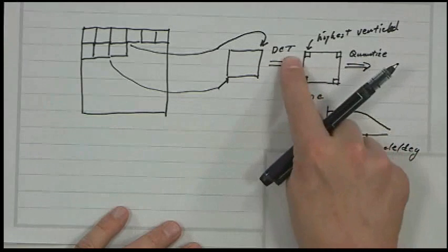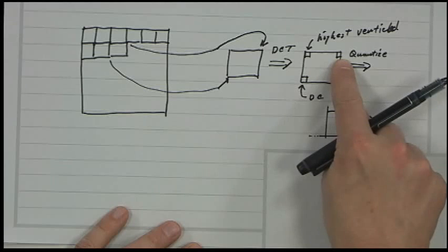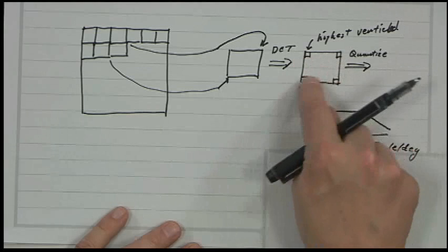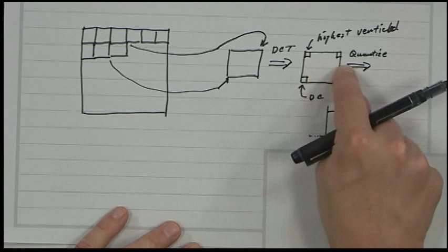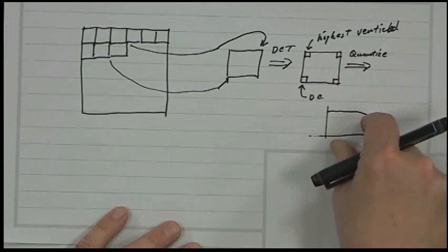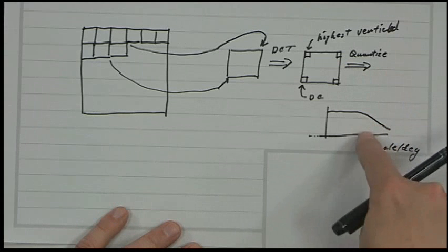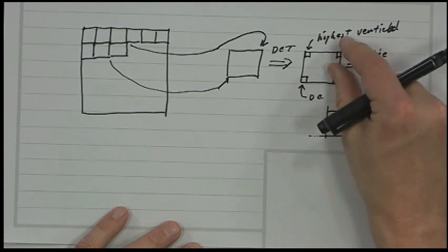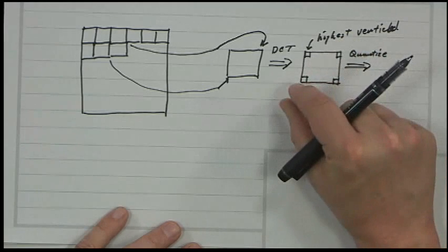But in any case, if you had uniform quantization, so all the values are quantized with the same step size, then you would be minimizing the mean square error distortion. But you don't really want to minimize mean square error distortion. You want to weight the high frequencies as less important. So you want a larger quantization in the high frequencies and a smaller quantization in low frequencies.